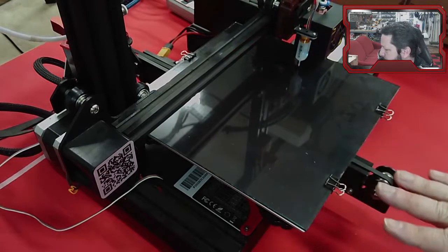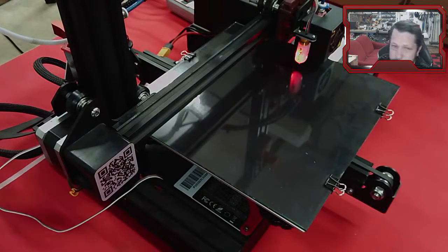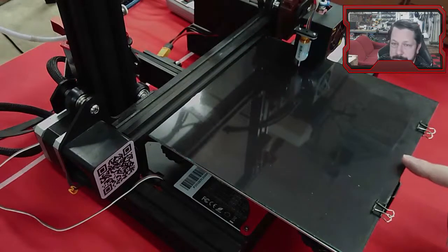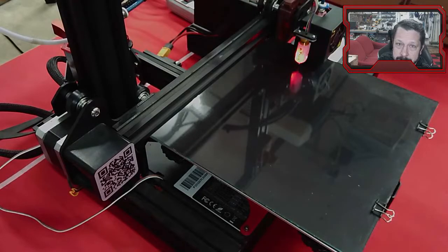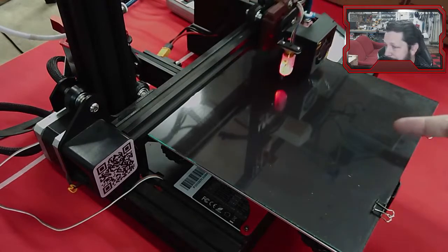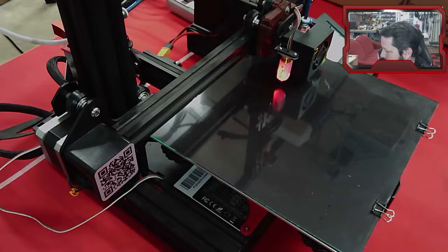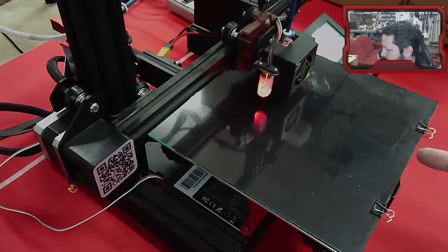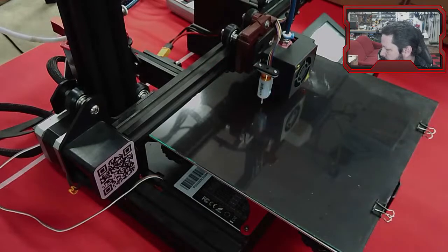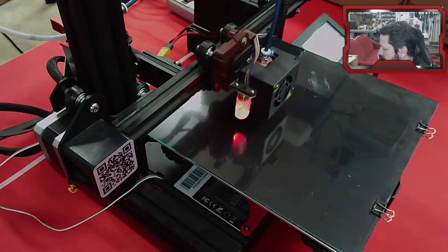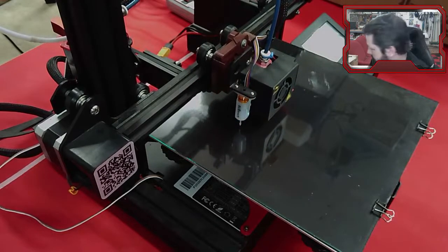On this side, you put a piece of glass on there, you print on top of that, and you're probably fine without the bed level. This is a super cheap upgrade, assuming that you're comfortable cutting glass. You can buy sheets of glass already cut to the right size. But this really is just the center part, or the corner part, of a Walmart picture frame. But you have to cut it yourself, right?